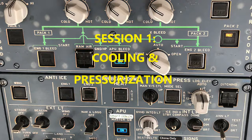If you need to reset the zone controller, there are different circuit breakers that have to be opened for so many milliseconds. So just check with your AMM and make sure you're resetting the correct circuit breakers. I don't want to mention what they are because, again, it may vary depending on the configuration. I just want you to make sure you refer to your AMM and follow the instructions at your MRO. But just so you know, you reset them through the circuit breakers. So that gives you an idea of the BITE test. The zone controller controls the built-in test equipment function for the temperature control system. It's monitoring its hardware and software, and it's going through 3 different tests: a system test, continuous monitoring, and lastly the power up test. So that gives you an idea of all of that.